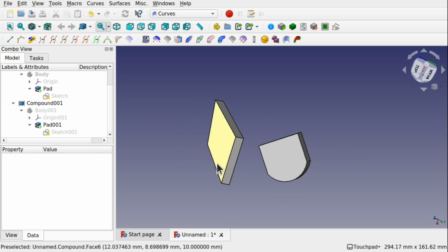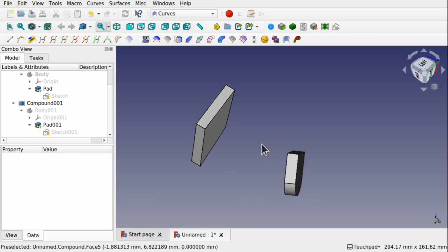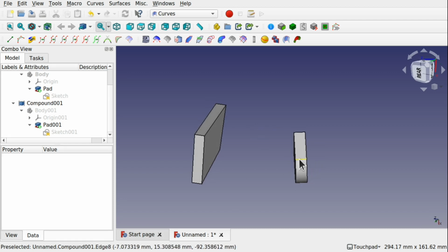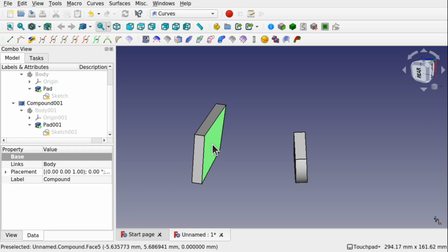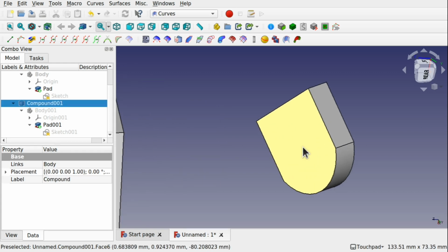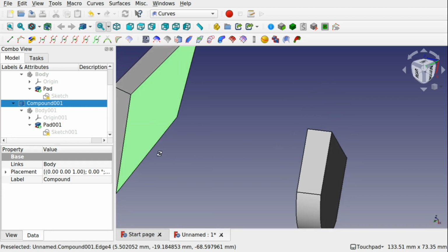So we've got still 4 edges, 1, 2, 3, 4 on both sides. We've got the diamond to this arc shaped body here, and we're going to do the same. We're going to click the face here and click the face here, control click both of those, and we're going to control click this edge and this edge, and we'll look for a corresponding edge on this side.